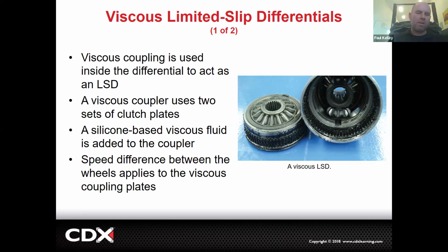Okay, we can do it better now than viscous fluid, but we could do it purely mechanically with viscous fluid. What we'll probably do now is an actual clutch pack, and we'll control that with a motor or a solenoid. We could even use pressurized fluid, like if it's a Subaru and the Subaru's got pressurized fluid through an oil pump, we can pump that clutch pack up with ATF or similar.